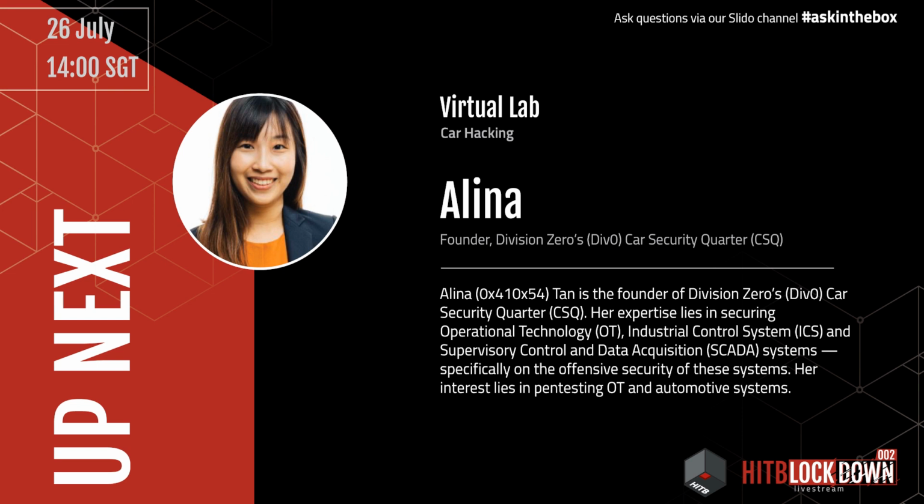But to interact with the vehicle itself, for a start, it would be better to connect via the OBD2 port, and you will of course need a CAN translation device, for example CAN to USB, or CANable Pro, or PyCAN. All these devices allow you to communicate from the vehicle to a laptop and vice versa. So there are also different ways to do so. It depends on whether you tap into the CAN traffic.